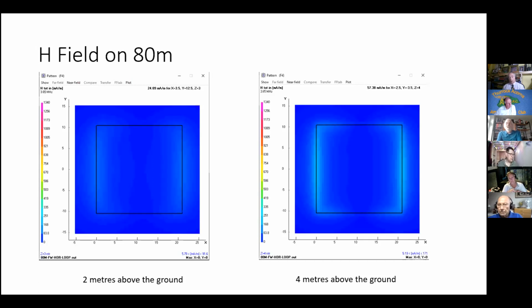Below 10 megahertz, because there is a concern over nerve stimulation by electric fields, which effectively acts instantly rather than accumulating over time, there is no averaging. And the 83 volts per meter is thought to be the threshold where those effects can be felt. So effectively the distance limit is only determined by power and the antenna geometry. If it has open ends, you need to keep that far away, below 10 megahertz.